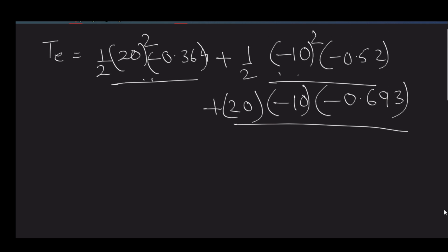And whenever they are not zero, you see that the expression of current is a square. So irrespective of the current flow, they only sense that some current is flowing and they will produce some torque, just to make sure the reluctance of the path is minimum.